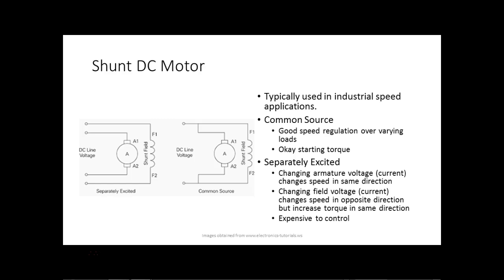We need a lot of torque to start the motor. Torque is proportional to current, right? How strong the field is. So why do we need a real lot of torque to start a motor? An object at rest wants to do what? So you got a motor, and we don't just use a motor to turn something. We use a motor to move things, right? You understand? So not only are you dealing with the motor being at rest, you're also dealing with the load that the motor's trying to move being at rest.